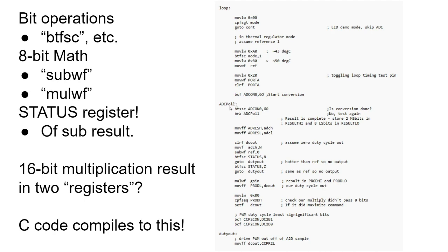We could make this interrupt driven, but in this case we're polling, and this loop is running at nominally 60 kilohertz. If we look on a scope, we would see that we are toggling this pin up here at nominally 60 kilohertz, which is 4 orders of magnitude faster than you'd need for a thermal system such as this. The time constant of that resistor is many seconds. We can model and analyze that as another exercise, but just know we are insensitive to sampling rate here. We are well oversampled, you would say.